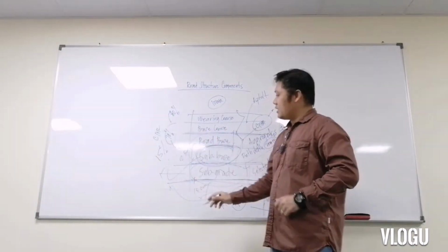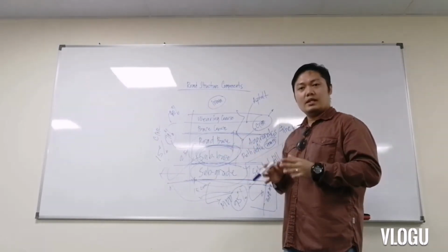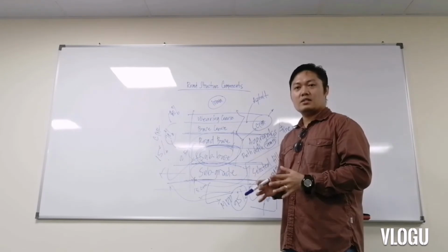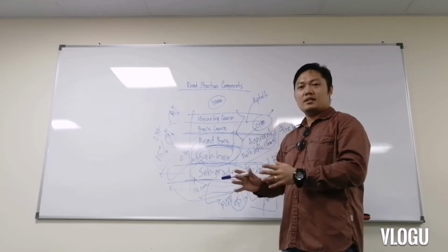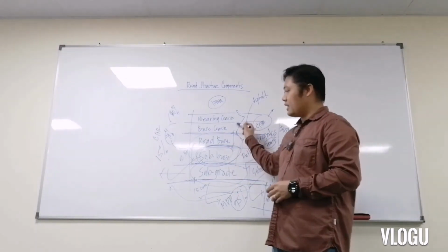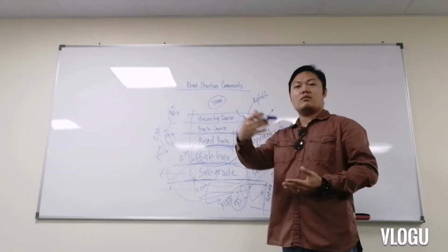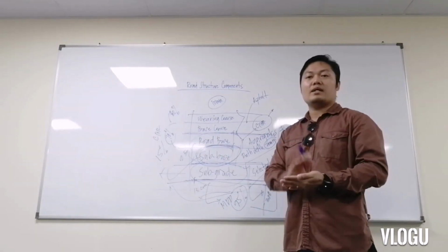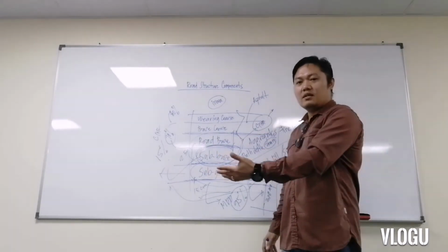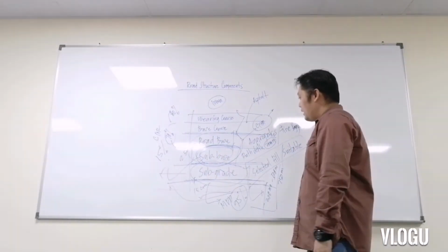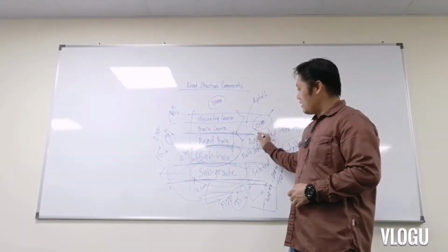Now, we have to ensure before we proceed with the laying of asphalt that all of the underground services, underground utilities, were already installed, inspected, and tested. So in the actual construction field, we have to ensure that all of the utility clearances have been verified, signed, and approved before we raise the scheduling of the laying of asphalt. Now, we are going to proceed with the laying of the asphalt road base.